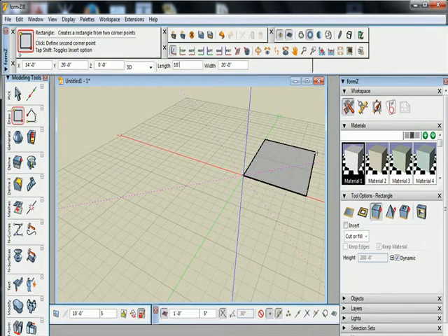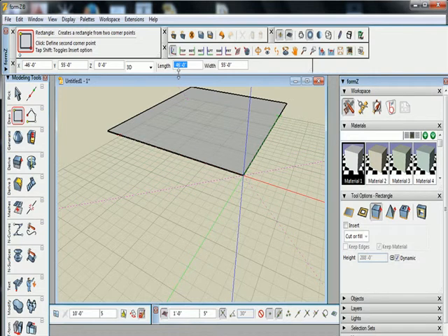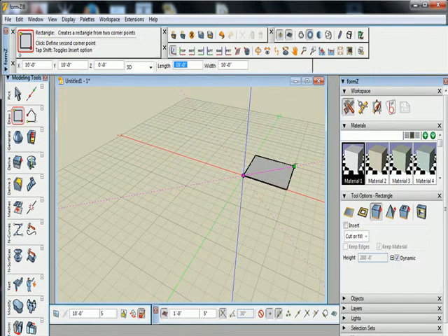Now don't touch your mouse while you're doing this. That's one key important thing, because if you do, that's going to take away your input right away. And for us who begin using these programs, it is just the most frustrating thing, because you'll have one hand on the mouse and one hand on the keyboard, and then you'll type in 18 foot, and then you move the mouse a little bit. Oh man, it's all screwed up. But you'll just kind of get used to it. So let go of the mouse while you're trying to input the number.